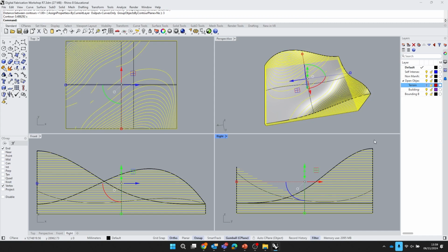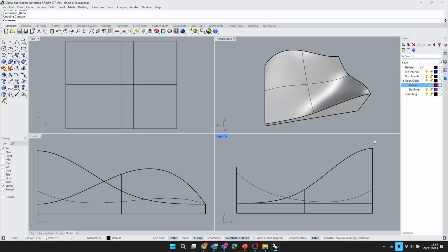and that will generate all of my contour curves as closed boundaries. What I need to do then is lay those curves out onto my sheet, onto my rectangle, 810 by 450, and then I can set those to a laser cut. Colour them red, give them to Scott, give them to Pete, they'll be laser cut. I just stack them on top of each other. And that could be as complex as you want it to be.